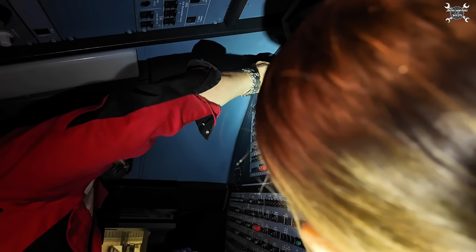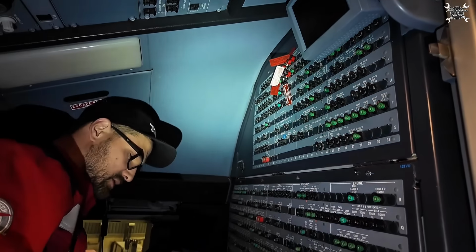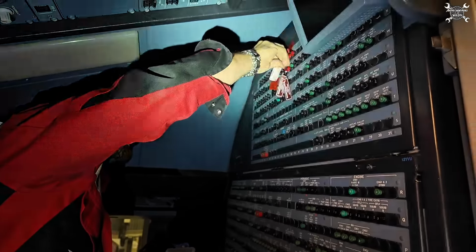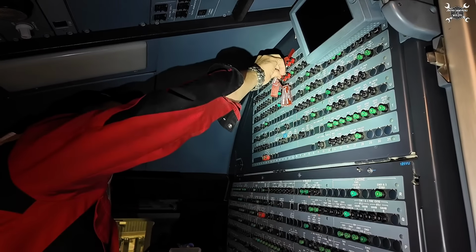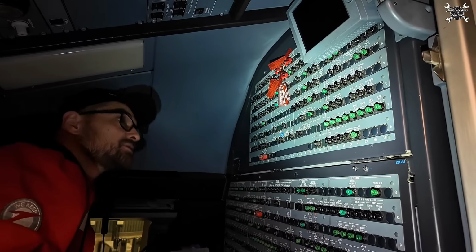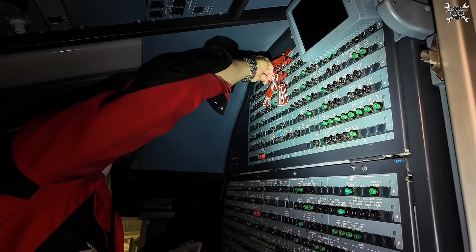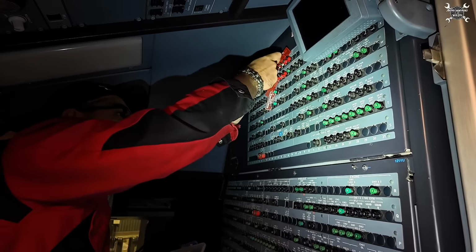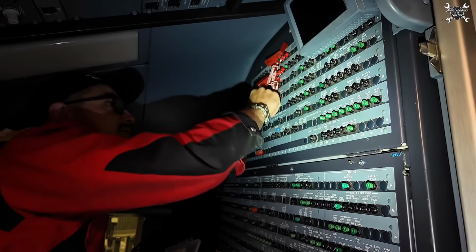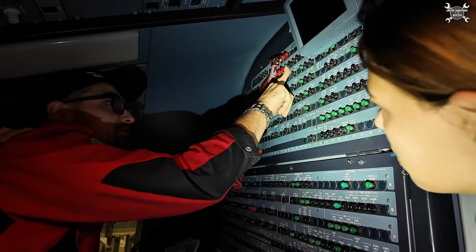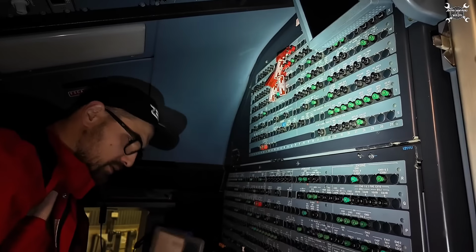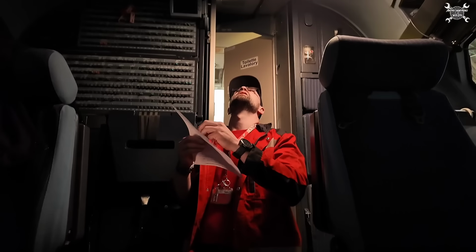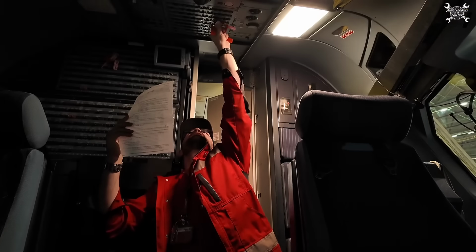Which are these now? These are probes, all the probes, because we might, since we maybe put the airplane in the air, this will start heating immediately. Or if you pull LGCIU, it also triggers the heating. But we'll see in the rest of the test. And the computer. If you pull the computer first, it will start heating. So you need to pull the probes first, and then you can pull the computer. Hey, there's a row. Yeah. And a few more CBs are remaining.